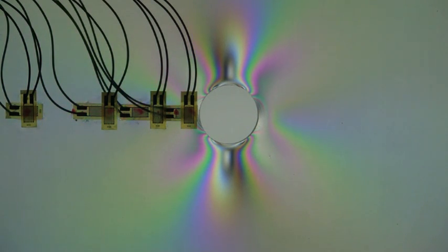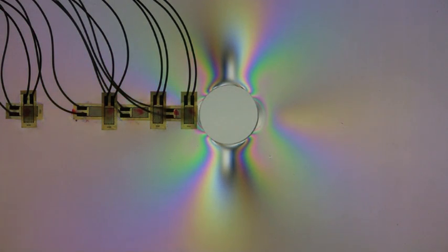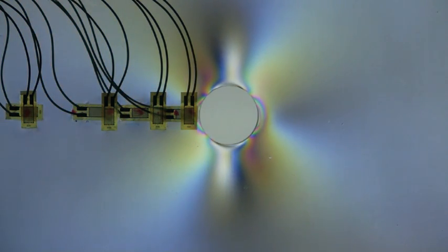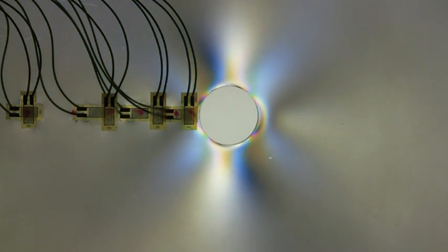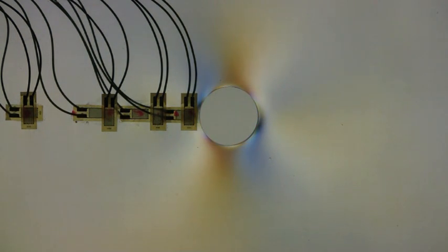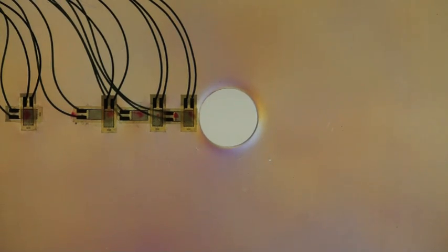This is because the material remained in its elastic region during loading. This means the maximum stress experienced by the plate did not exceed the yield stress of the material, and there was no plastic deformation. The Instron machine also showed that the material behaved linearly throughout the entire process, indicating that the proportional limit was not exceeded either.